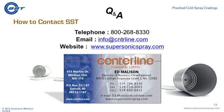Yeah, Hastelloy, stainless steel, Inconels. These are all nickel super alloys that are used in chemical, nuclear, and industrial applications where corrosion resistance and mechanical durability are designed into the materials. I hope the audience can appreciate that the corrosion resistance of the surface resulting from cold spray coating is fully dependent on the coating material that you start with, the choices that you use. What can SST cold spray currently spray? Well, stainless steel 304, 316 is quite common now for us to apply as corrosion resistance barrier coatings. We can spray Inconels. Our Series EP running on helium can spray some of the harder materials for corrosion resistance.